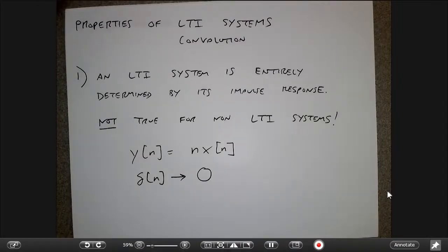But in some situations, it may be hard to get an input signal that is really loud for an instant and then turns off. So instead, I could provide a system that turns on and stays on, like a step function. That may be an easier signal to physically produce. Then I could measure what I get, and turn that into the impulse response later.